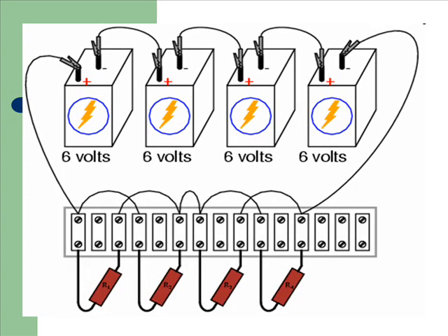Building a circuit with components secured to a terminal strip isn't as easy as plugging components into a breadboard, principally because the components cannot be physically arranged to resemble the schematic layout. Instead, the builder must understand how to bend the schematic's representation into the real-world layout of the strip. Consider one example of how the same 4-resistor circuit could be built on a terminal strip.